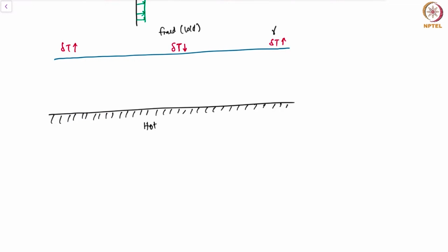The surface tension on the sides, because the temperature is slightly higher, slightly drops there, but the surface tension in the middle is slightly more. And again, as you know, the fluid would be dragged from regions of lower surface tension to higher surface tension. So at the interface we have a motion in this way, which is basically along the interface,